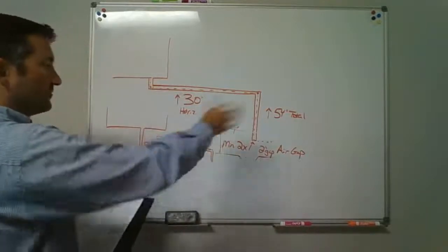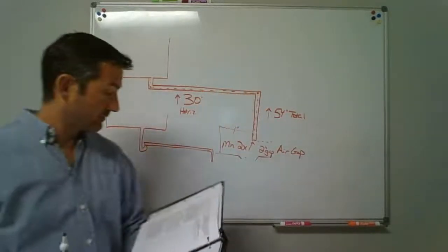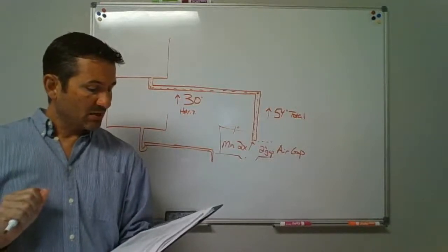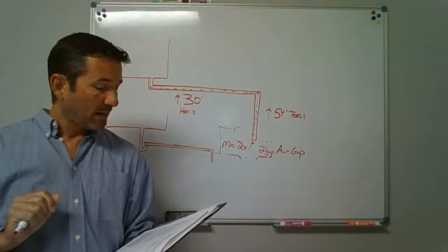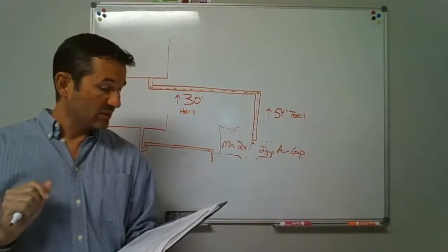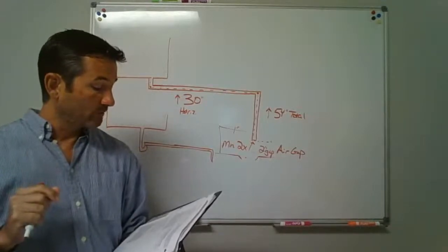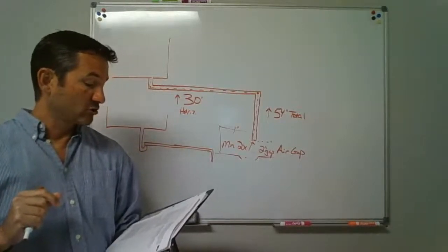Some way of getting that as far as just not allowing that water to splash everywhere. Hub drains. Hub drains shall be in the form of a hub or a pipe extending not less than 1 inch above a water impervious floor and shall not be required to have a strainer.